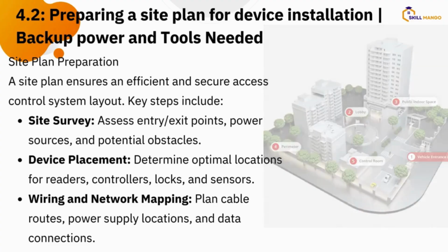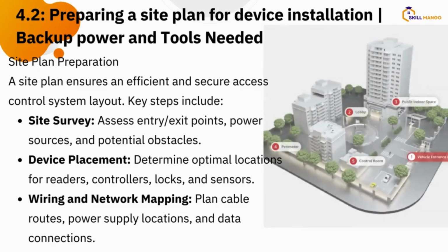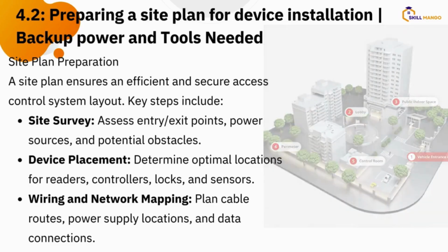So it powers the entire system, and they're all functional. Then in terms of a centralized solution, this same standalone door will now be wired to the control panel using network cable. This also has to be factored in and planned for at the initial stage. So when you get to that point, you know that we already have the pipes that link from each door to the central point, which is where you have your door controller. It could be a 4 door controller, a 2 door controller, or an 8 door controller.